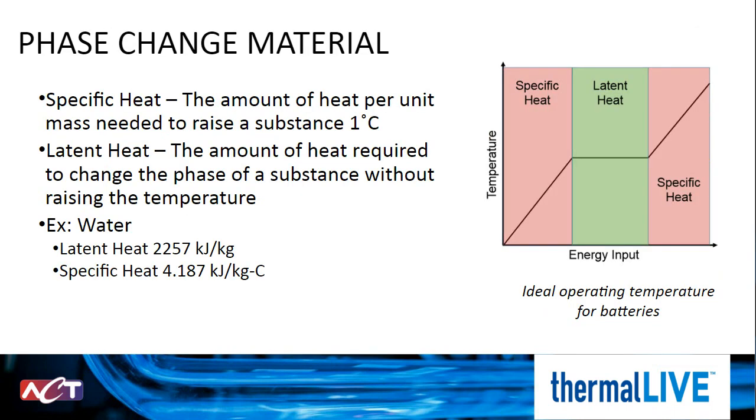The final technology we're going to look at is phase change material. Now, phase change material heat sinks operate as a thermal battery or thermal capacitor. They leverage the latent heat of fusion as shown on this chart to store high amounts of thermal energy over a given period of time. A PCM solution would be able to hold the battery to a distinct temperature for a longer duration. This solution, however, requires space for the PCM and adds weight to the vehicle.